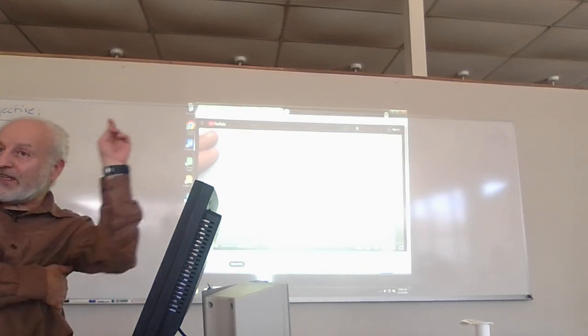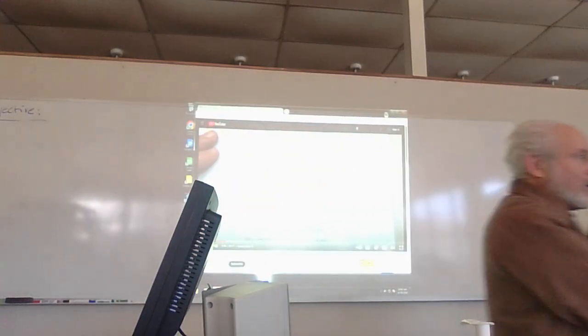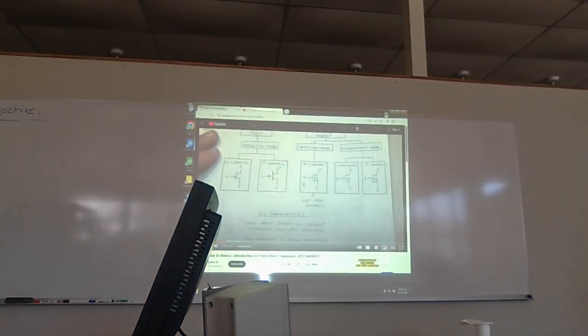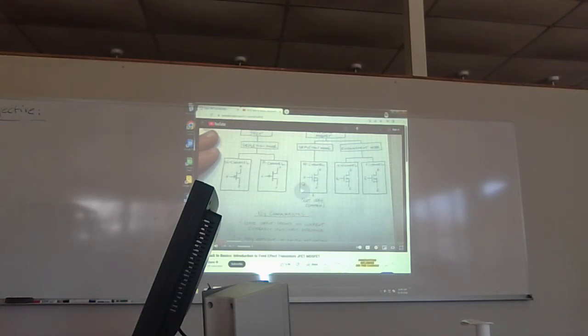Not as efficient, as we've seen in an example in the previous video, in terms of amplification. We only had about a 3-times amplification there. And again, this is a voltage-controlled device, not a current-driven device. But still, there's more output signal than input signal. There are certainly a lot of other characteristics too. Chapter and verse has been written around FETs, but these are the major differences compared to, say, bipolar transistors.